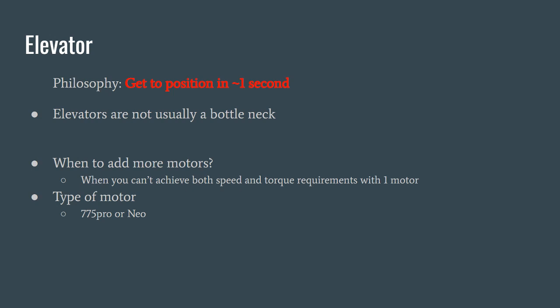Do you know what powered takeoff is? Does it have anything to do with pneumatics? Yeah, it's something to do with pneumatics. You have your drive gearboxes, right? But when you're climbing or doing something in particular, you might not be using the drive base. So what people did was they would have a pneumatic that would cause the drive base gearboxes to shift. So they're no longer connected to the wheels of the drive base, but the gearbox is connected to like an elevator or like a climber of some sort. So it's a way to change what your motors are connected to by throwing a pneumatic.